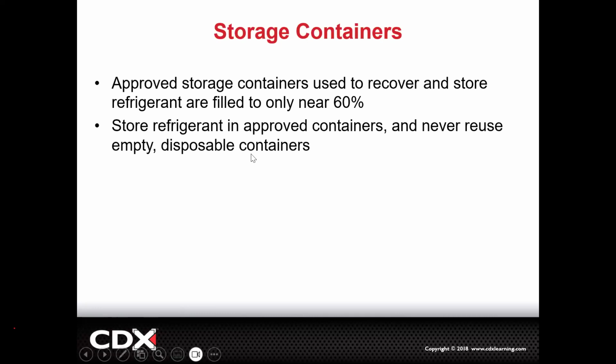It's just made to charge the car. It's not made to recover the car. Makes sense? So if it's like the little blue one for R134a, you can't use that as a recovery tank. They also have a check valve, so you literally can't. It won't work. Okay, but they're not made for that anyway.